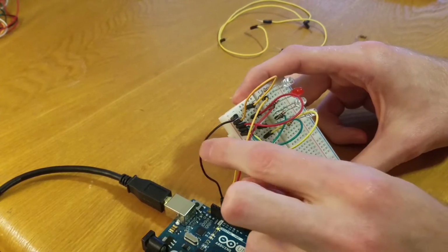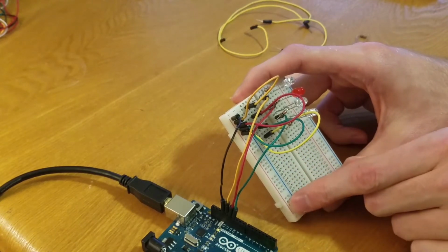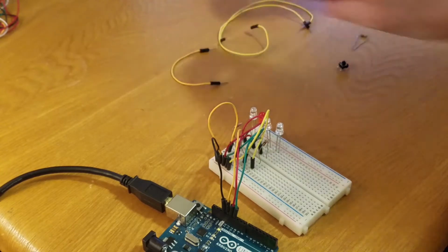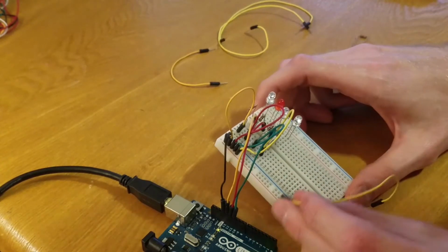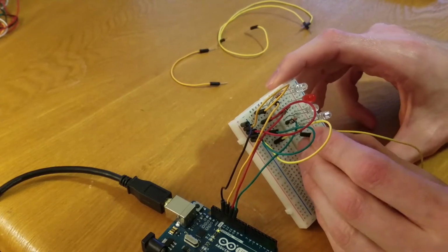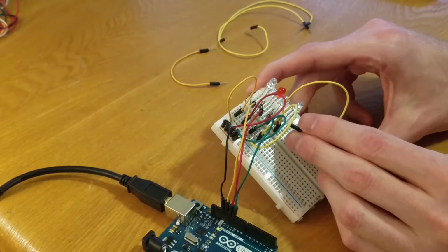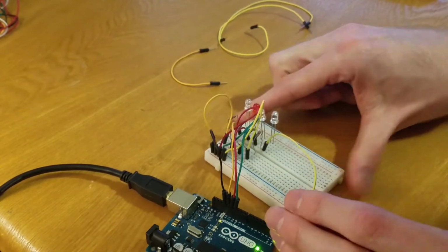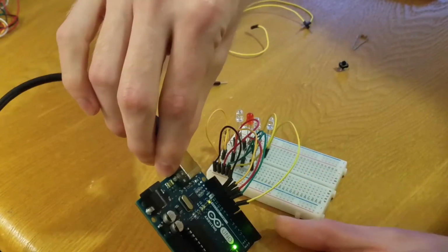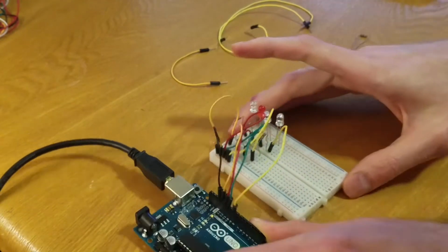Okay, so only one ground line goes to your board. The rest of my ground lines will go to this plus symbol. Right, the second line that we need is going to be to the right pin. All right, so I'm going to come back over here on line 11 of the third column, right underneath the resistor. And then the second side of that goes to, we'll skip down one, so this will go to 9. Okay, so 9 on the digital pin.